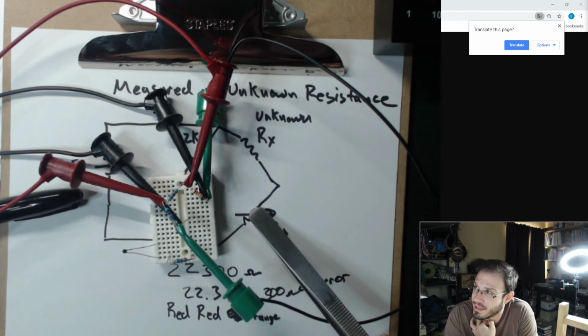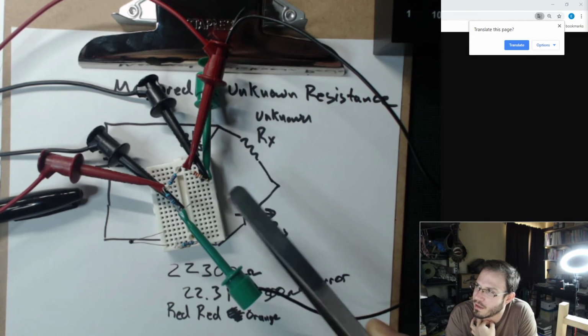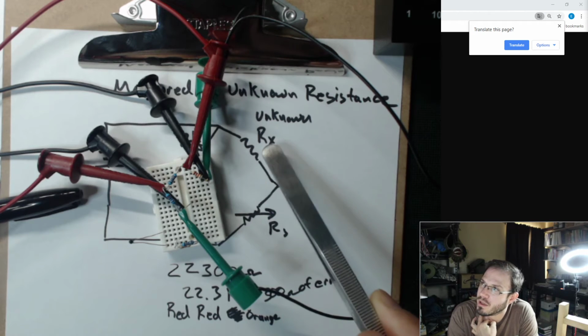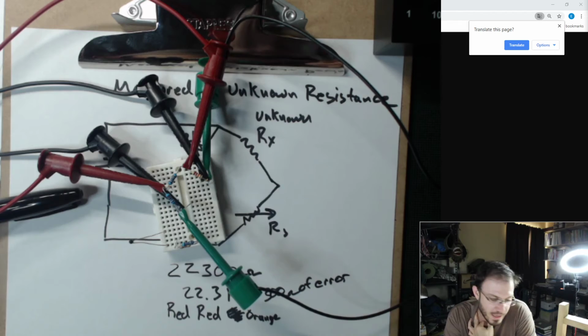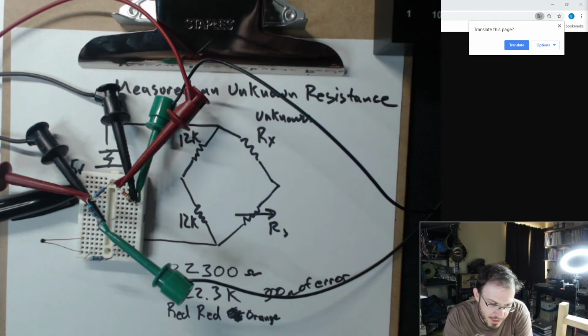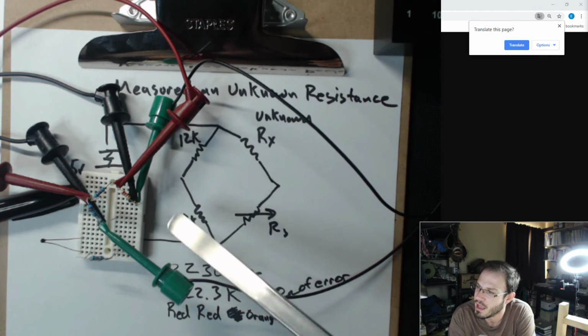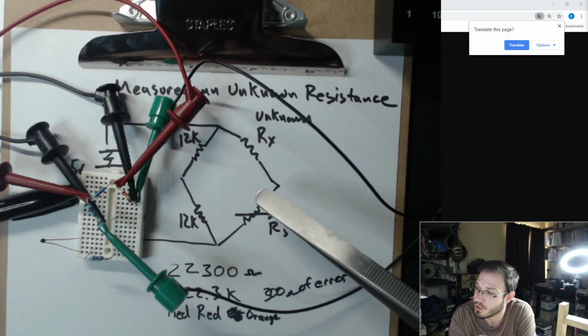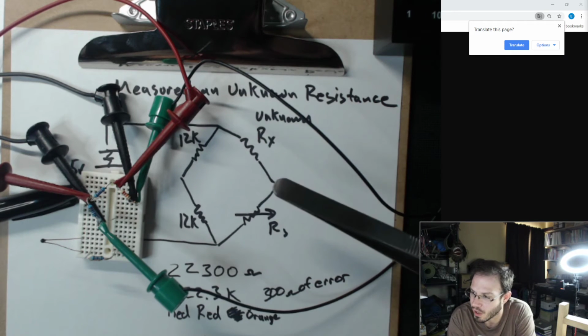We would actually fix this to be another fixed known value resistor and then just use the voltage drop between both to figure out what the value of our sensor is. So that's actually what I'm going to do next. But does anybody have any questions about this resistance substitution box, the bridge circuit we've looked at thus far? It is a very simple circuit, and we should actually be able to understand this very easily given what we've learned thus far.